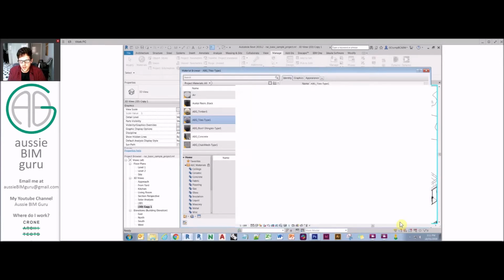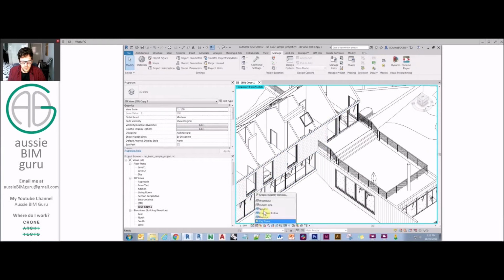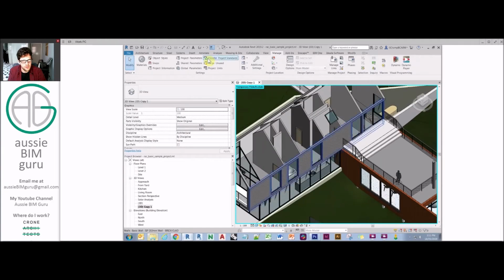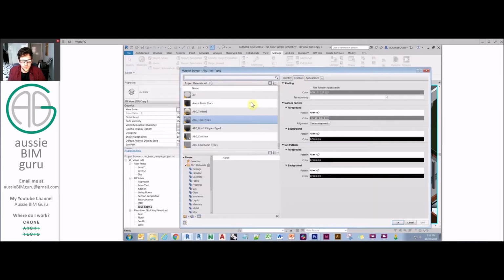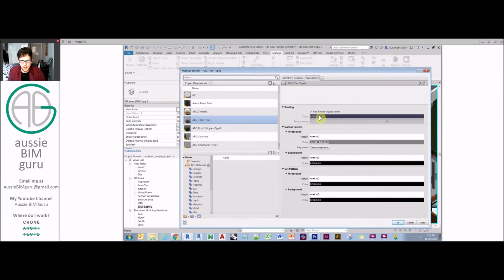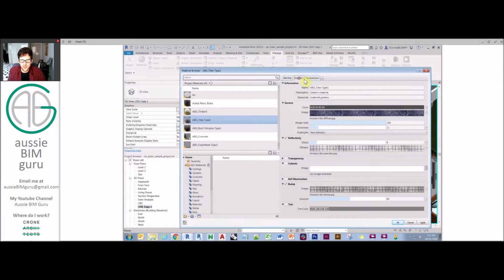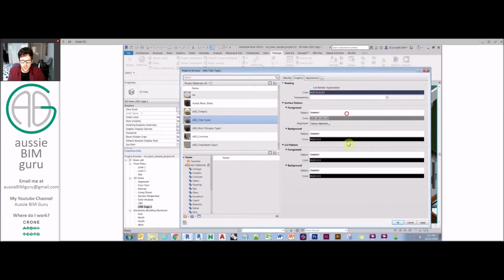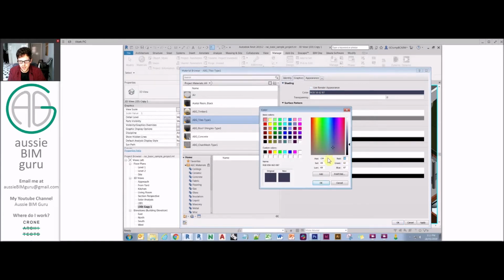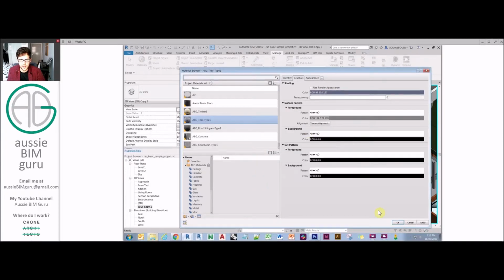And if we just okay that, so anywhere we have that particular material, actually before I move on, one last thing to show you before I tag this: if you want to change the shade of the appearance, you can always just say use the color that my material reaches overall, but obviously that's quite dark, so you may want to then release it and amplify this by maybe 40 in each slot, so 102 and 127, and that would give you roughly the color.